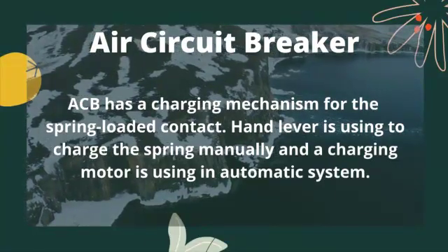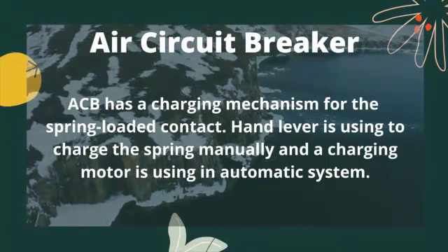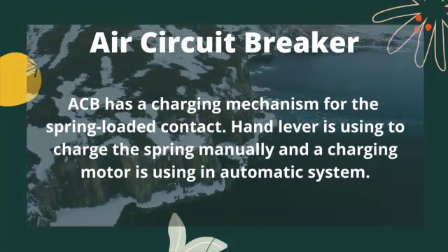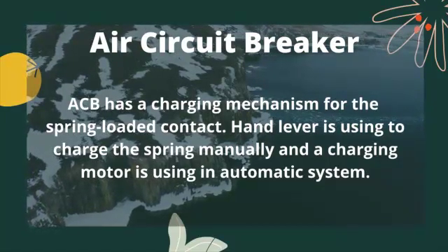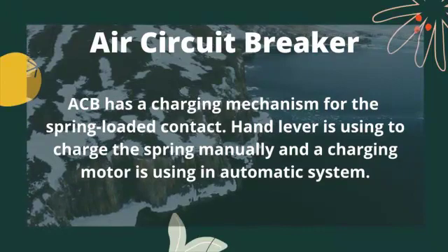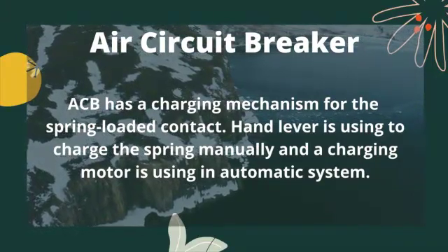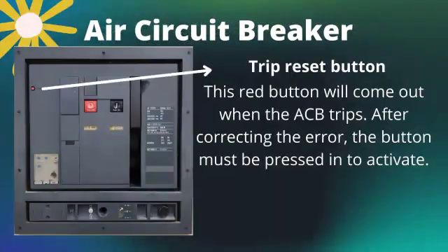ACB has a charging mechanism for the spring-loaded contact. A hand lever is used to charge the spring manually and a charging motor is used in an automatic system. Know the ACB in detail.